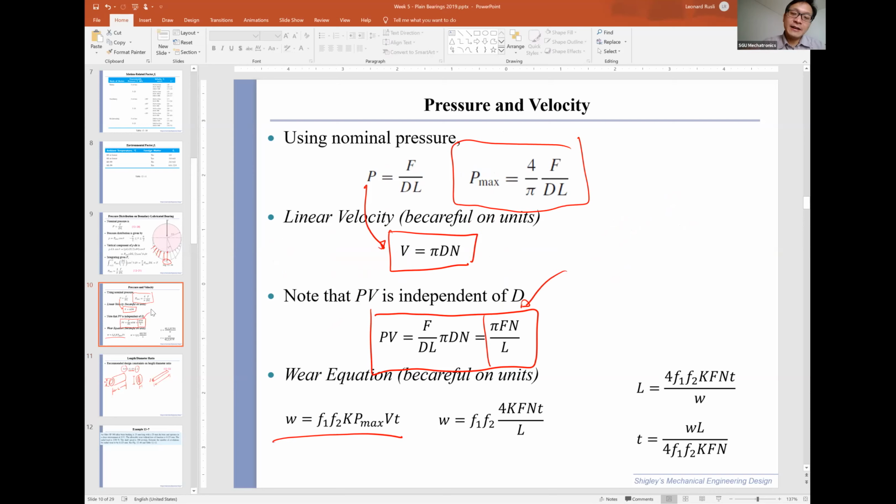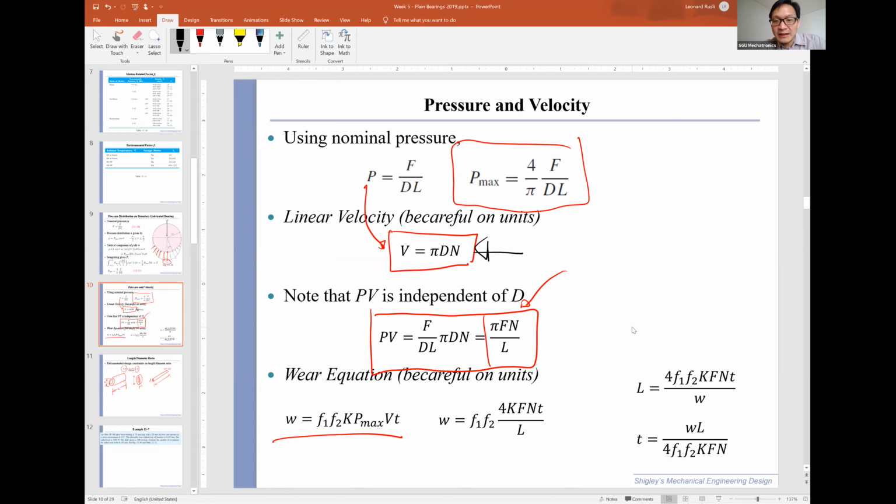Well, maksudnya begini. Kalau diameter kamu lebih besar, ya, notice this thing. Kalau diameter kamu lebih besar, velocity-nya lebih besar kan? Okay, if I rotate this shaft, and you stand on the edge here, let's say you're Ant-Man standing on that rotating shaft. Now your speed going forward will be V equals omega R, correct? So the greater the R, the greater your V.